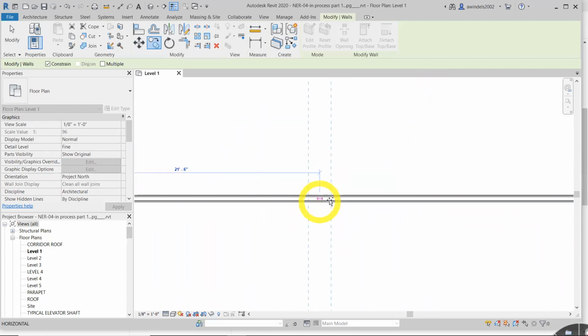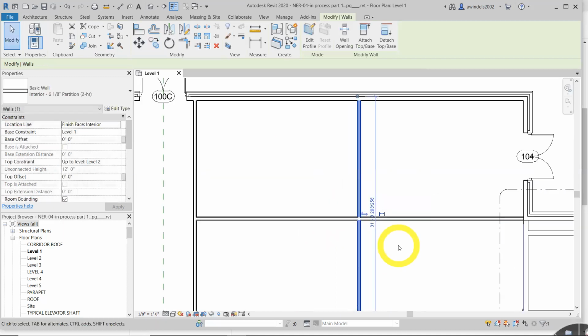You got to hover really surgically in there. Sometimes I find when it's copying, it's staying constrained on this middle line. You can see that little magenta arrow. It doesn't allow you to leave that line, which is a good thing in this case. And there I hovered and I found it. Or you can type in SM for snap midpoint and it'll go to it more quickly. It'll find it. So that's what that was trying to do. The wall was just already there.